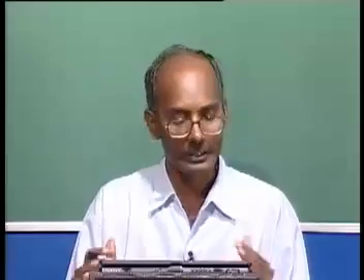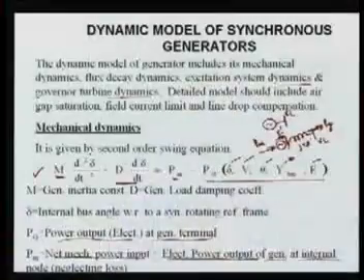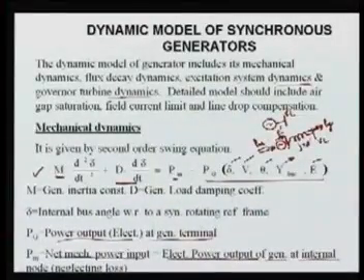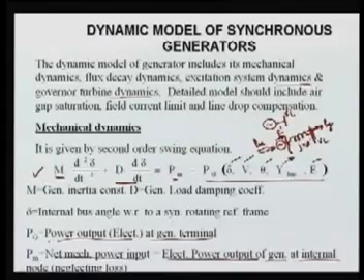If the machine losses are neglected, then this can be equal to the power output at the internal bus. So that's why the electrical power output of generators at the internal node is written here rather than here. This is your terminal voltage, and that is your electrical output at the generator terminal. So this is the difference between P_G and P_M.